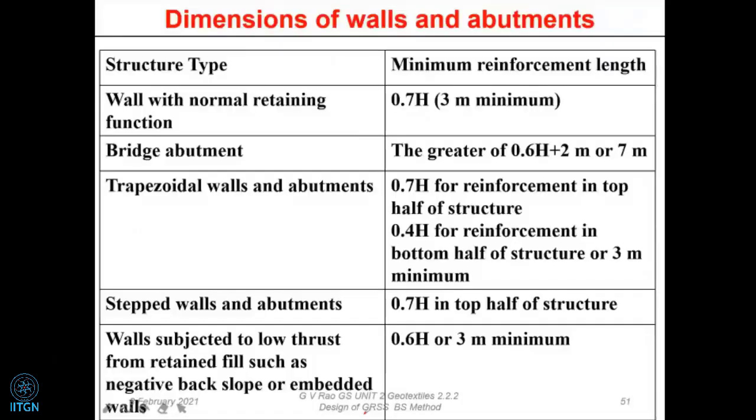Okay. Now in step one, we said this is sizing. What did we say? We said that for a normal, plain retaining wall, the nominal length of the reinforcement which you are going to pick up is going to be 0.7 times the design height. I think I mentioned also, H is not the actual height of the wall, it is a design height.